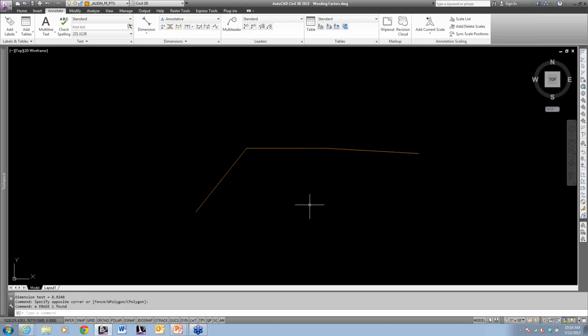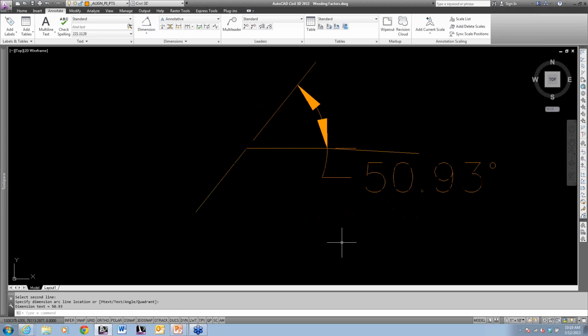The next thing it's going to do is take a look at the angle. Is the angle less than what was listed in that dialog box? And the angle that it's looking at is the turned angle. Is this turned angle less than the value? And the default value is 4 degrees. So if I throw an angular dimension in here real quick, just so we can see this easier, you can see this most definitely in this case is greater than 4 degrees.